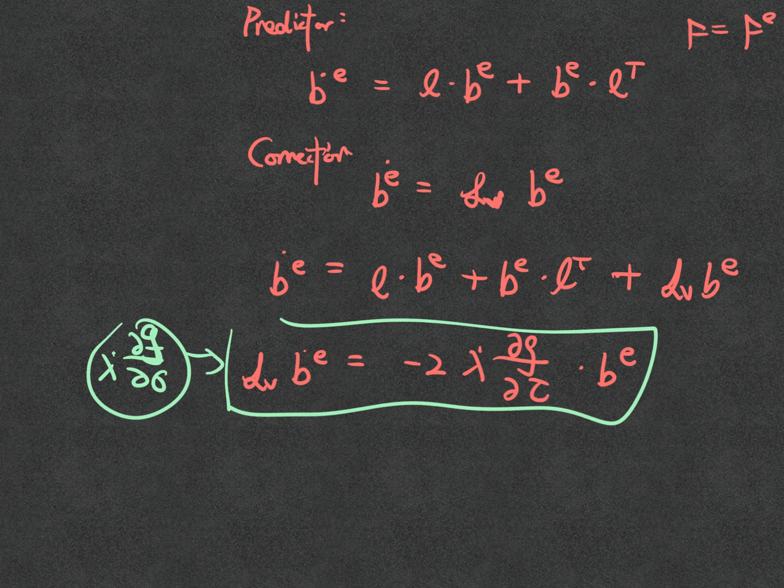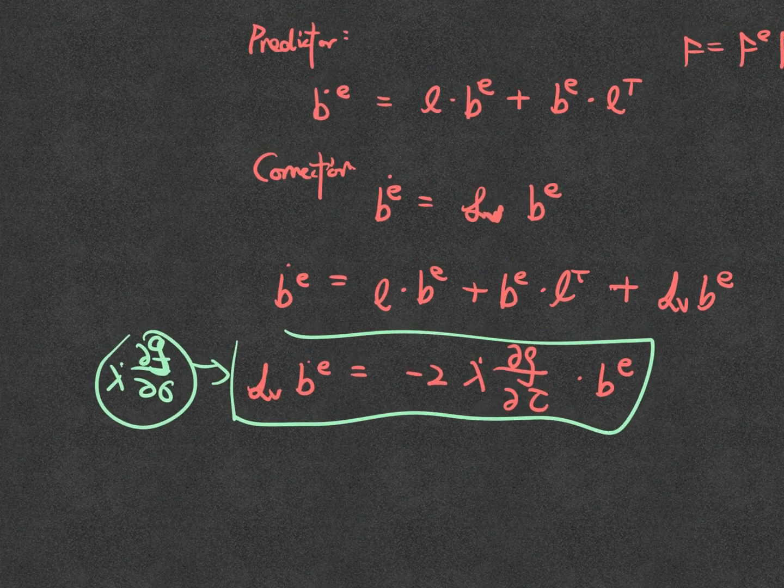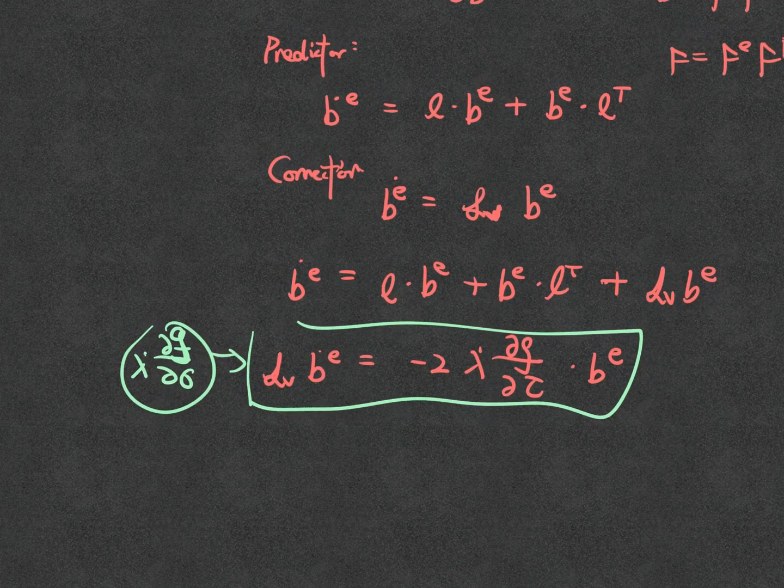So how would that algorithm work? I would use the spectral decomposition to decompose B into the spectral directions, leveraging the fact that B and the corresponding Kirchhoff stress share the same basis.